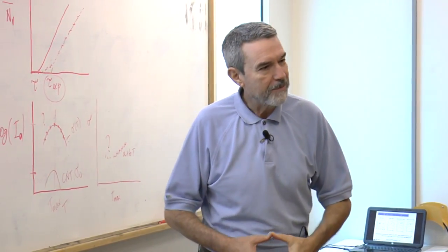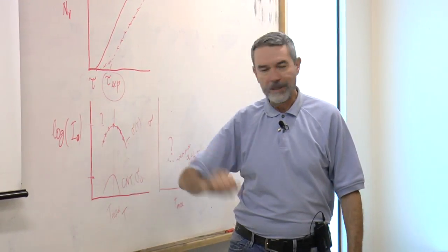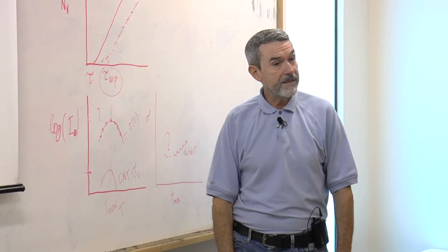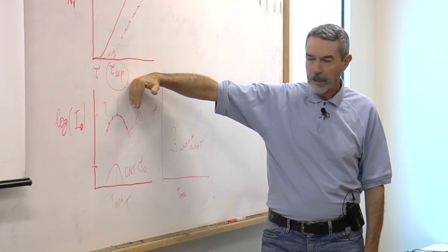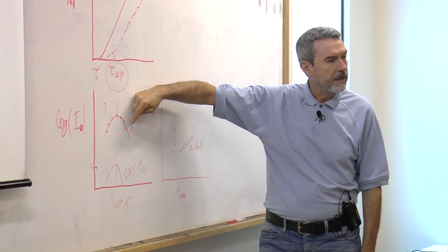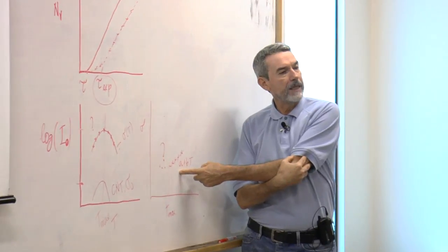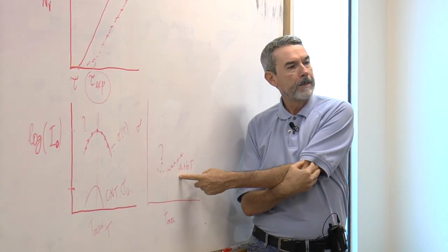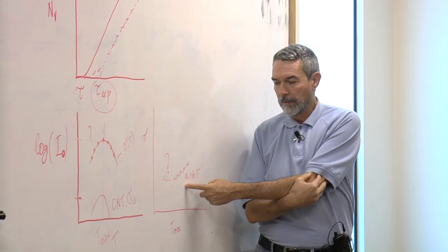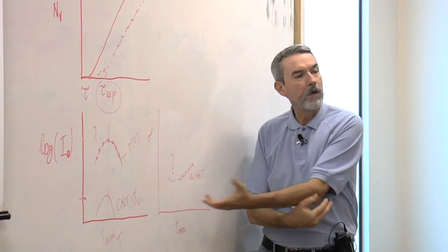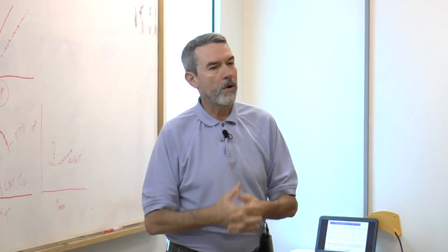It does not describe the nucleation rates below Tmax. The current state of the art is, above Tmax, we can perfectly describe the nucleation rates using, for instance, a temperature-dependent surface energy. But we cannot describe what's going on below the Tmax or below the Tg, because they both coincide. This is still an open problem.